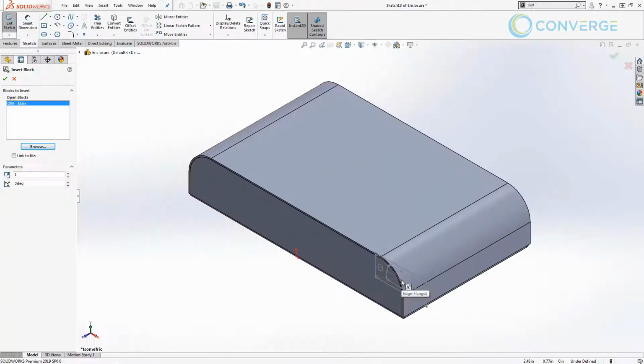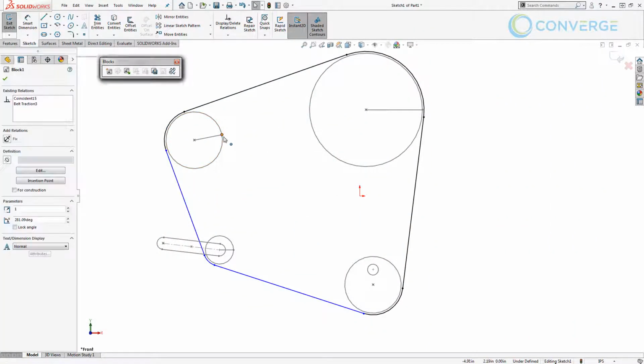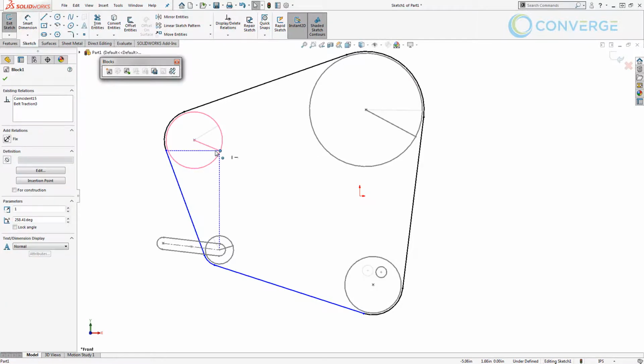If you've missed the first two, in the first one we covered the creation and usage of basic sketchblocks. The example we used was a DB9 connector. We learned how to create the sketchblock, how to save it, and how to reuse it to create features on parts. In the second video, we talked specifically about the belt and pulley layout, where we created a basic layout of pulleys with tensioners. We used the belts and pulleys functionality and engaged it so we could have rotation. Then we also talked about ways that we can reuse that information to create solid geometry.